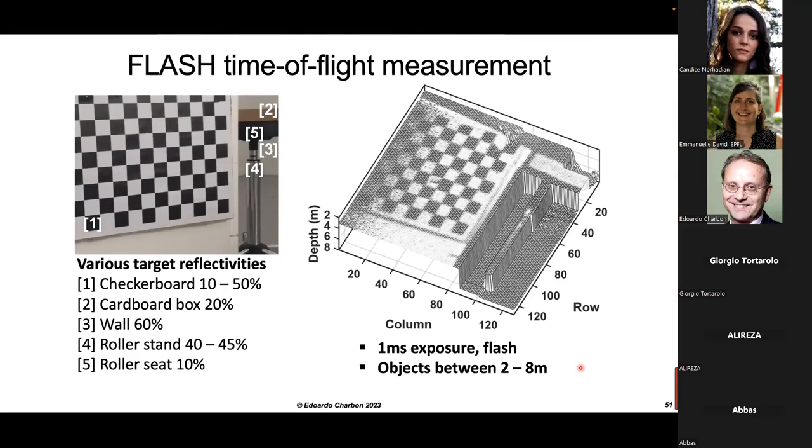There's one effect that we have observed, which is interesting, known as RTS, random telegraph signal. So what happens is that the DCR changes between 2 values, or in some cases 3 or 4 values. And this is due to traps that are introduced by irradiation. So the RTS pixels is usually a very small number of pixels.